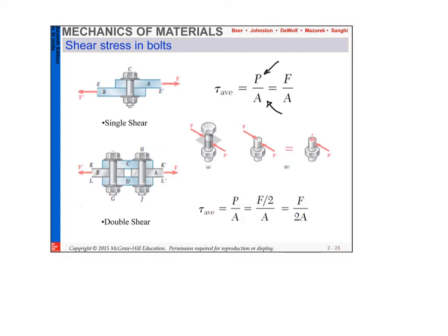When we get to the actual shear stress, we should have what we call the transverse shear stress. Might be covered this semester, might not be covered. But as far as average shear stress, which is represented by tau, our average shear stress equals P divided by A. Again, this here is a single shear, and that one here is a double shear plane on bolts.